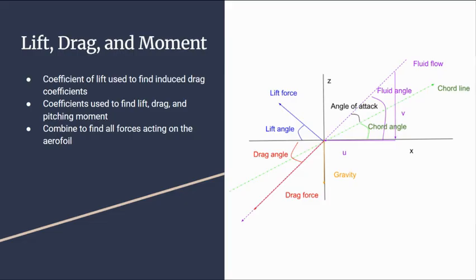So instead, we estimate drag using two pieces: the induced drag, which comes from the lift distribution, and an average parasitic drag coefficient measured experimentally through wind tunnel testing. This allows us to approximate total drag well enough for flight dynamics modeling, even though viscosity isn't explicitly included in the theory. Once lift and drag and moment are known, they feed into the equations of motion.